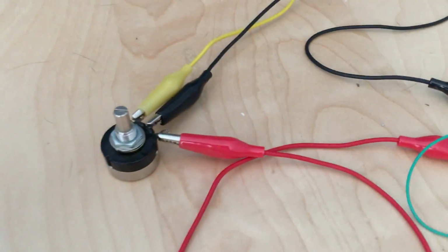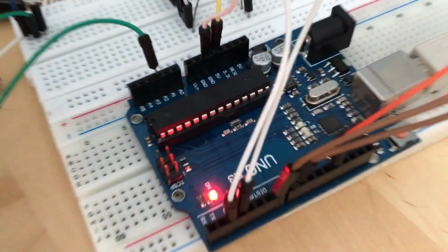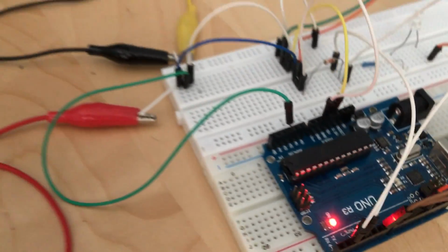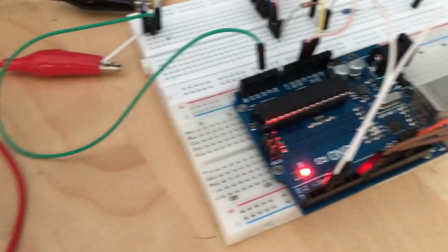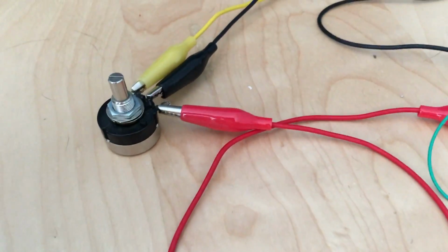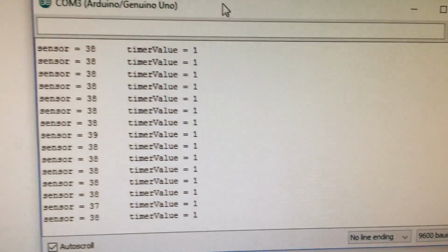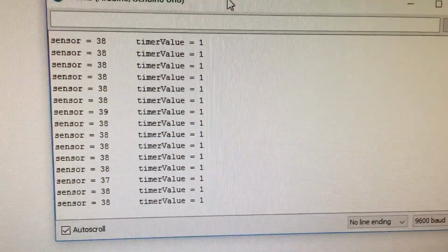This is used on the potentiometer feeding into the analog input of the microcontroller that has an onboard A to D converter. This converts a voltage signal from the potentiometer into a digital reading that can be then used to set various things.